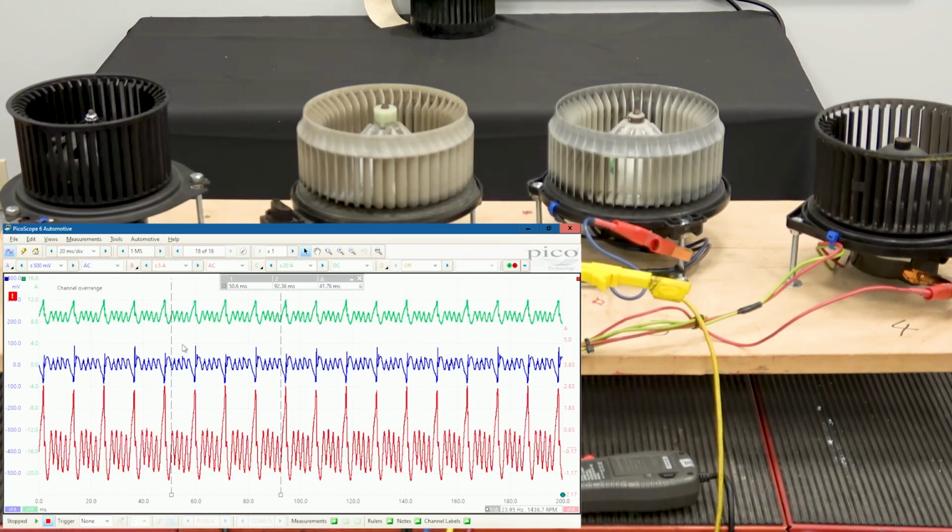And again, the top pattern here, the green, is DC coupled. It's on a 20 amp scale. That's just the straightforward current for this motor. On average, it's open air here, so it's not pulling a lot of current. It's pulling about 9 amps. Blow motors in the case could be pulling 15 to 25 amps, which would be pretty common on a lot of motors when they're actually in the case forcing air through the system, drawing it through the filter and pushing it through the system.